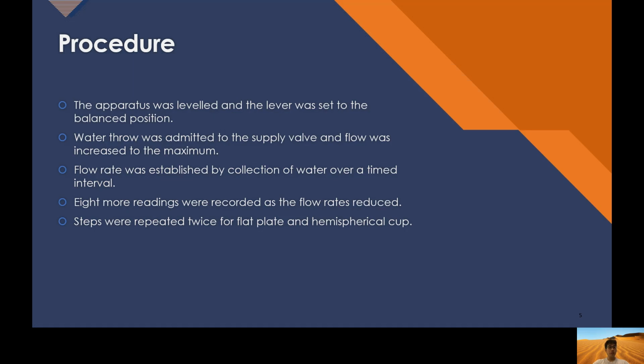As for the procedure, the apparatus was leveled and the lever was set to the balance position. Water flow was emitted to the supply valve and the flow was increased to the maximum. Flow rate was established by collection of water over a time interval. 8 more readings were recorded as the flow rates reduced, and the steps were repeated twice for the flat plate and the hemispherical cup.